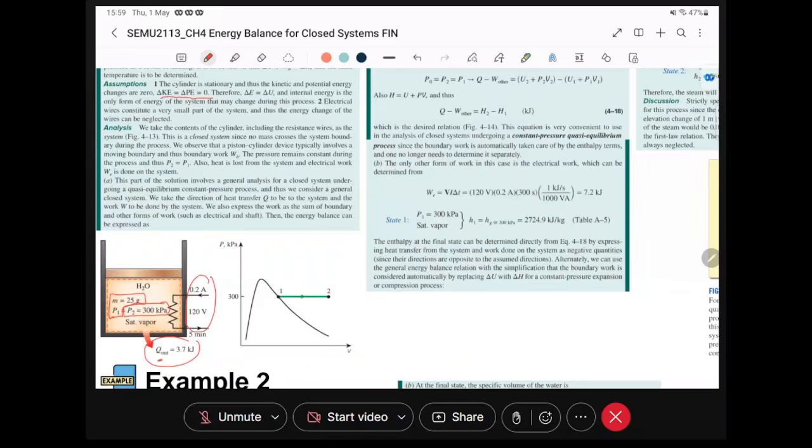This heat loss, and therefore it's a Q. This is work in, basically. Okay, and it starts from saturated vapor and then go to superheated. Okay, if you remember, the constant temperature line goes like this. Constant temperature line. Okay, so obviously 1 to 2 is not a constant temperature, okay, but it's a constant pressure.